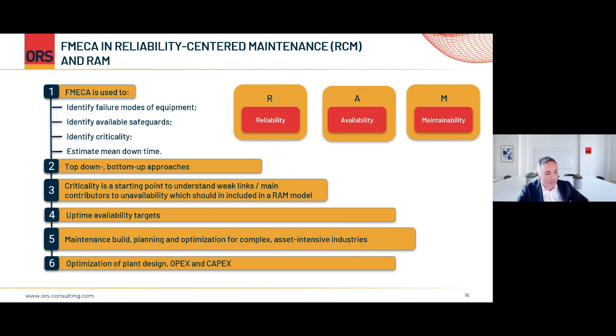Imagine that some of our clients develop large complex facilities, safety critical facilities, right? As a part of it, at one point during the detailed design, they will have to understand very clearly what components and what systems are safety critical, and what systems are production critical, etc. That is typically understood by high level FMECAs at the system level. One level down, we will need to understand in those systems what components are critical, if it is production critical and safety critical. And further on, for the critical components, we need to understand what parts and what failure modes are critical, and in which sense: is it safety critical, production critical, or can we just let it run to fail, so to say?